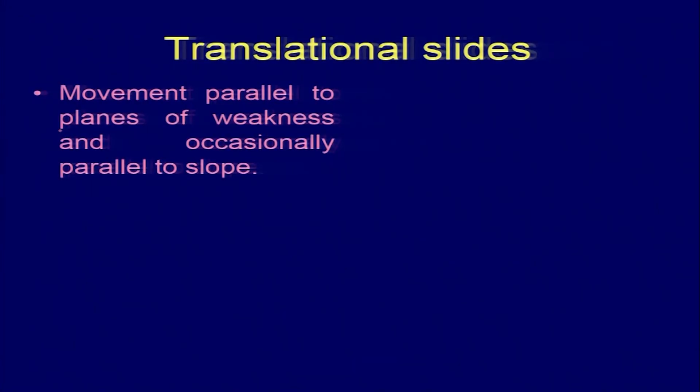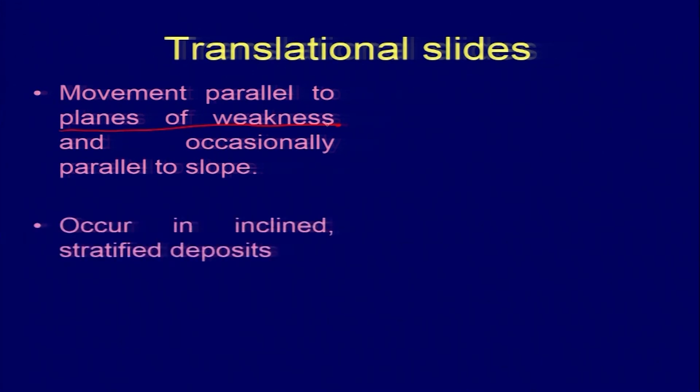Translation slide, movement parallel to a plane of weakness. That is what we were talking about on that day, that if we are having geological structures which are having a definite plane or bedding planes, that can result in the landslip, and this can occur when you are having inclined stratified deposits. As a thumb rule, all deposition will take place in a horizontal fashion.